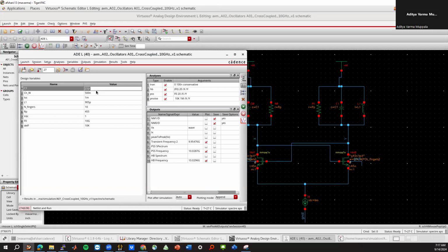It's closer, maybe 275 femto. Depends on how much you care about this. Okay, so that has changed a lot now, actually. So let's go back to 270 femto. You can also play with other results. We'll do that. So the next thing you want to look at is the phase noise performance.